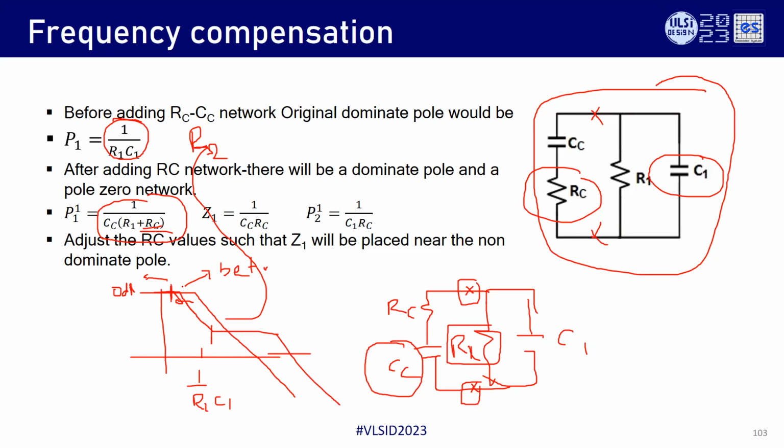But the point is your dominant pole will go down and the second pole will increase, provided these two compensate. They don't strictly need to cancel, but if you see the phase, it will come with -90 and there is a little bit of glitch and comeback because of the separation of the pole and zero. So here it's almost like a Miller, but without any high frequency power supply coupling.